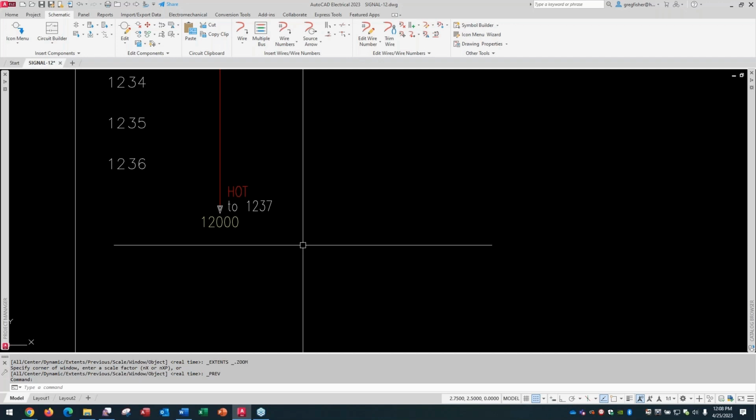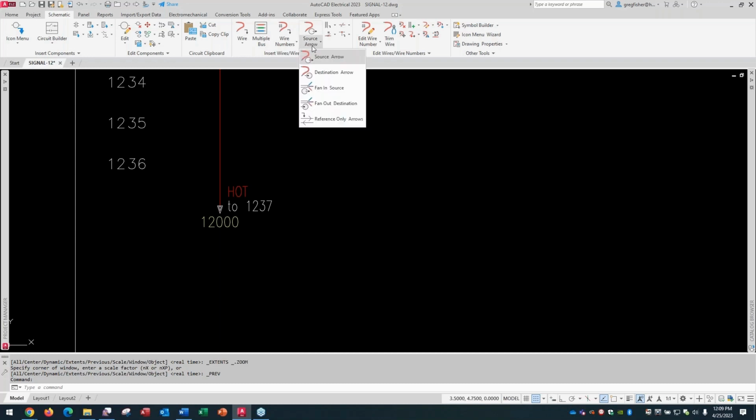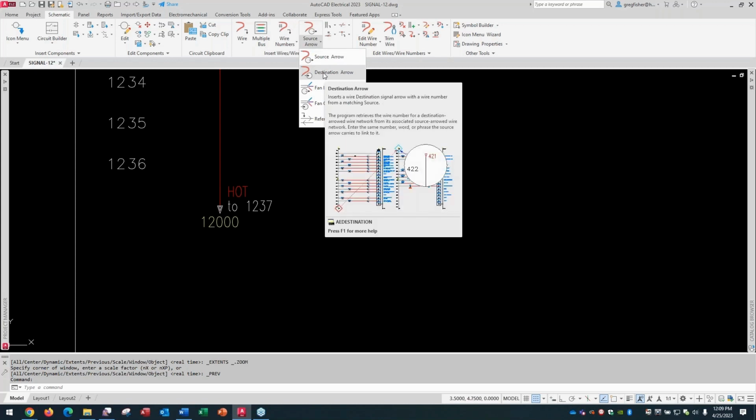Now, best practice wise is to take an existing one, copy it to your own custom folder, and modify it in your own custom folder. That way you can continue to use the command as is, but it's just going to replace the symbol out of the box with your symbol. And like I said, these symbols are not your standard push button, pro switch, whatever. They have a utility that's part of the symbol itself, doing the linking.